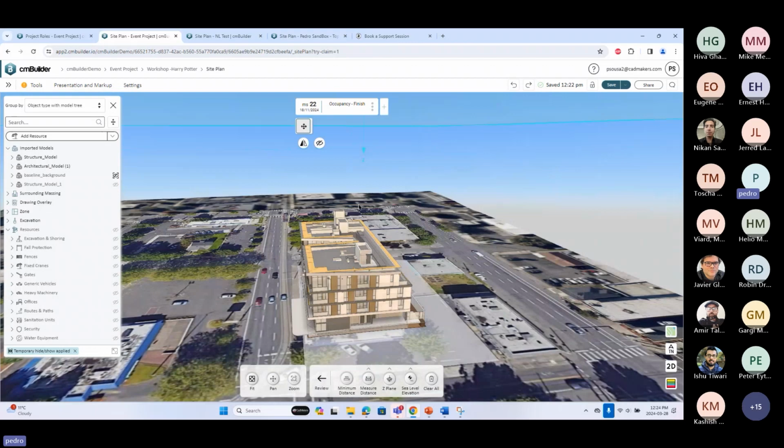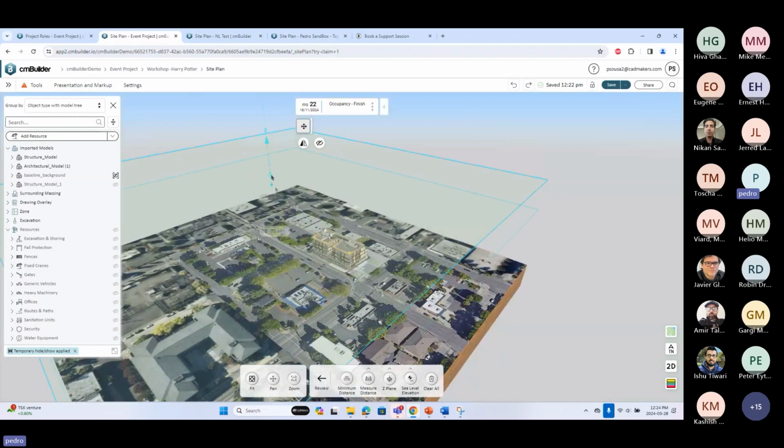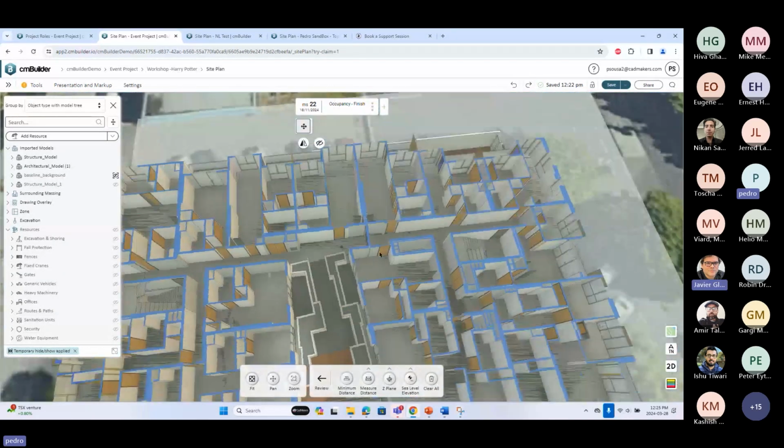And now you're going to be able to see whatever is inside of that elevation. This button over here, we invert the section so you can see it from the bottom, or you can see it from the top. And this other button will toggle the visibility of your sectioning. So you see the plane is gone. For me to now adjust that plane, I just have to clear the section and start again. This way you'll be able to see what's going on inside your building.